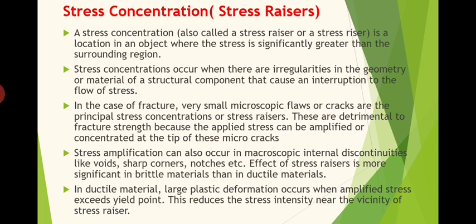A stress concentration, also called a stress riser, is a location in an object where the stress is significantly greater than the surrounding region. As the name indicates, stress concentration means stress is concentrated at a particular region of a material more than the stress experienced by the other regions. That particular area where the stress is maximum is known as stress concentration.